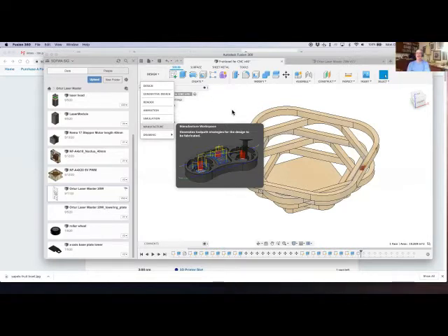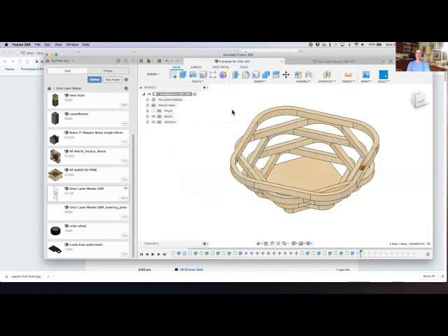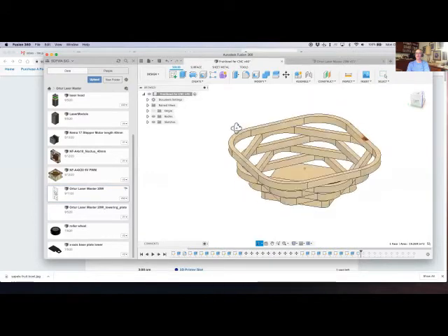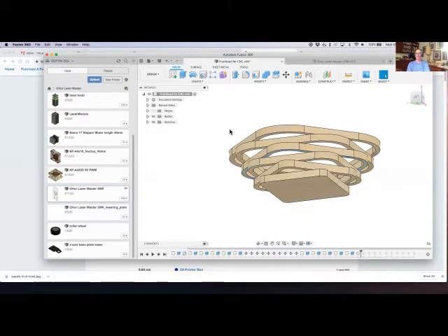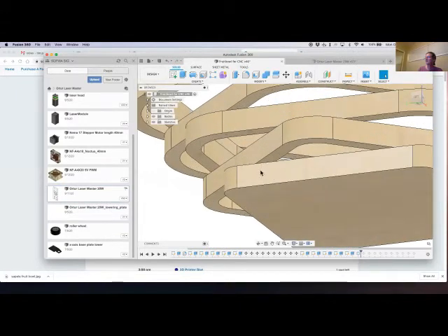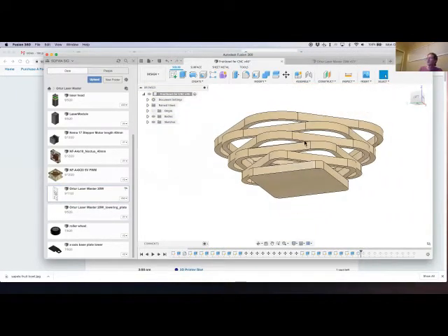Well, I think it's a cool little project, and everything is pretty straightforward except your little holes. The holes are not beginner content. Yeah, the holes are a little bit weird. And in order to get the tooling holes, I did have to machine from both sides.